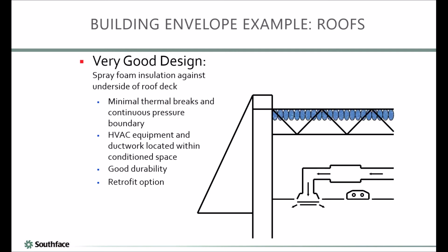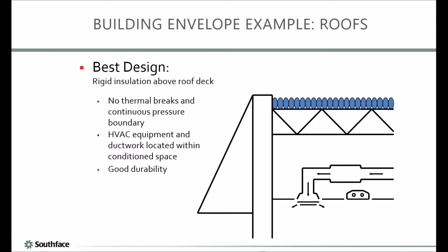In some cases, particularly as a retrofit, you can spray foam up against the underneath of the roof deck. That foam would most likely have to be coated with an intumescent coating as a thermal fire barrier. But this is better because it probably won't fall off and you can't really poke a hole, but the wall is still subject to it. Arguably the best place for roof insulation is continuous above the roof deck. And we want that to happen. We're still saying, though, that this should be a ducted return instead of trying to use it as the plenum, because of the real world.